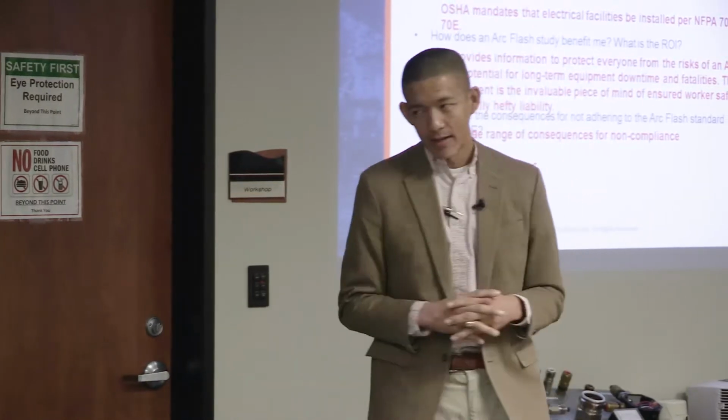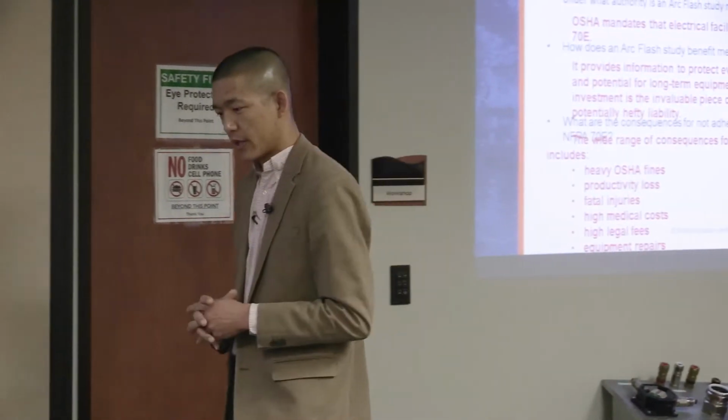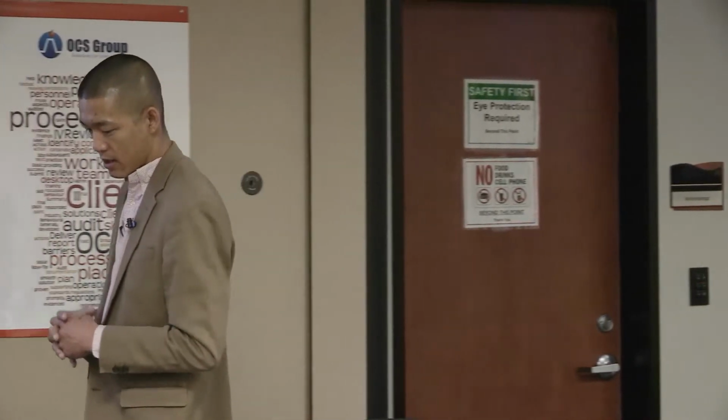One of the other things that they did remove, which I'm not very comfortable with, in the 2018 70E is the dangerous 40 cal per centimeter squared. They're no longer, since they're pushing you more towards doing a risk assessment rather than the calculations, it's almost telling somebody that where we used to consider the 40 cal the cutoff line where you shouldn't work on the equipment, it's almost saying that if you do calculate something more than that 40 calories, go ahead and wear a 100 cal arc flash suit and you'll still be safe.